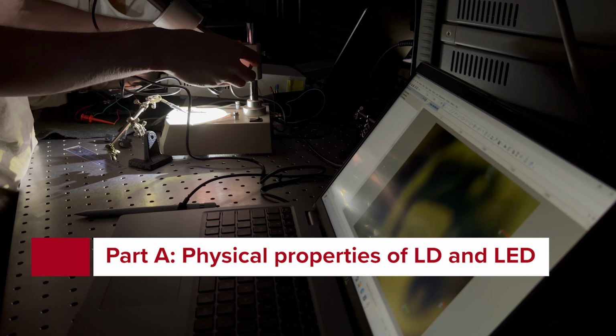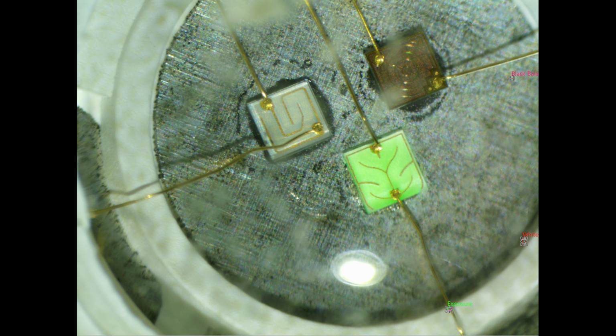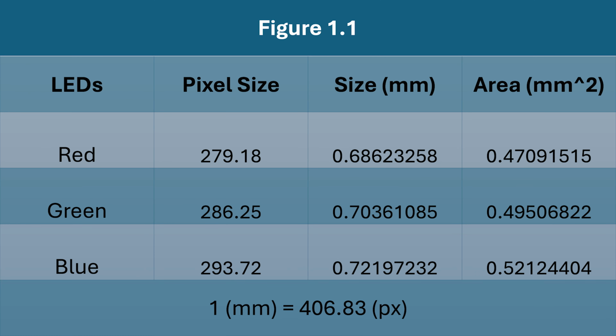In Part A, we examined an LED and a laser diode, LD, under a digital microscope using Thorlabs imaging software. After calibrating the microscope with a ruler, we determined how many pixels equaled 1 millimeter to size each device accurately. By adjusting the drive current, we viewed the red, green, and blue emitters of a variable LED, each with an area of about 0.5 millimeters squared, or half the expected area.